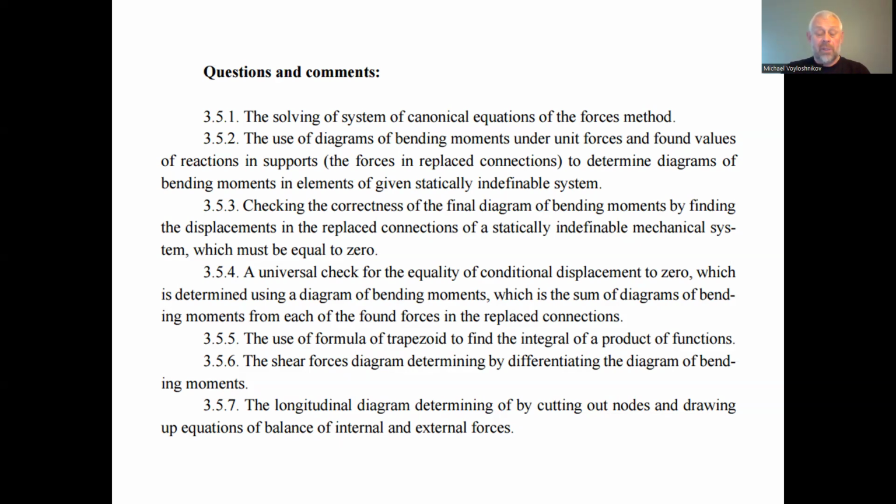3.5.6, the shear forces diagram determined by differentiating the diagram of the bending moments. So when we have the diagram of bending moments, we can find the diagram of the shearing forces. This is not difficult to do if the diagram of bending moments is linear, as in the considered case. The shearing force is a derivative of the bending moment for each segment of the considered mechanical system.